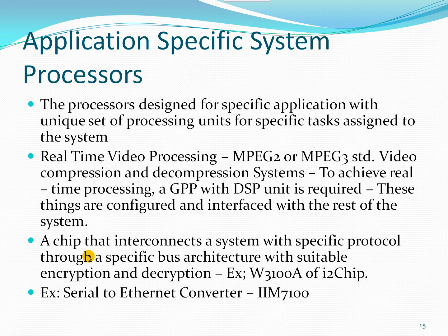We need to have a DSP unit in order to handle the DCT and FFT algorithms. A GPP with a DSP integrated into an embedded board is not an economical solution, because the GPP will be working at a given frequency, but the DSP unit will be working at a much higher frequency.